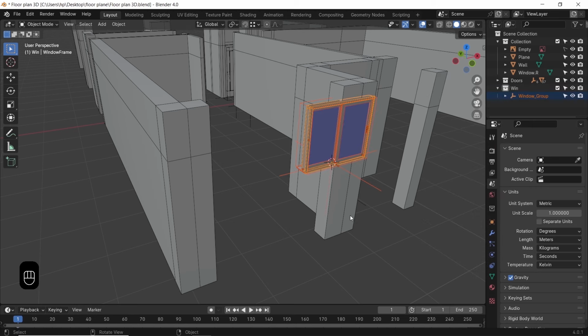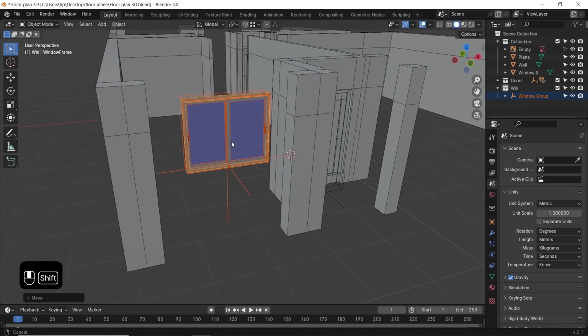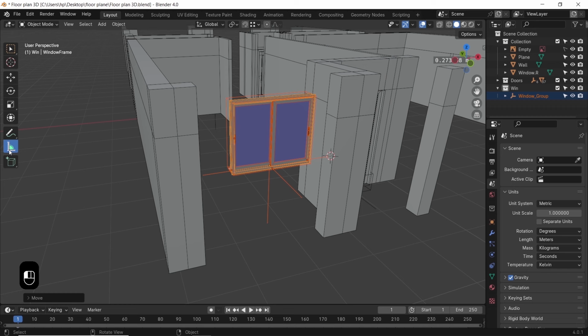You can also use the measuring tool to fix its width from the parameters, and it's the same as the door options. So select the window's frame to open the settings on the sidebar, and go through them if you want.